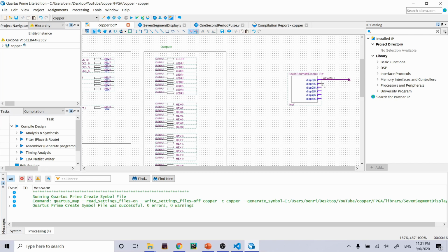Alright. And for the next one, we're going to do something similar, but of course it's going to be hex 1. But again, we define the bus. So note that when you're drawing the line or the wire or the bus line in the schematic diagram, the notation for vectors is different. Use this dot dot instead of the colon. I mean, it is what it is, right?